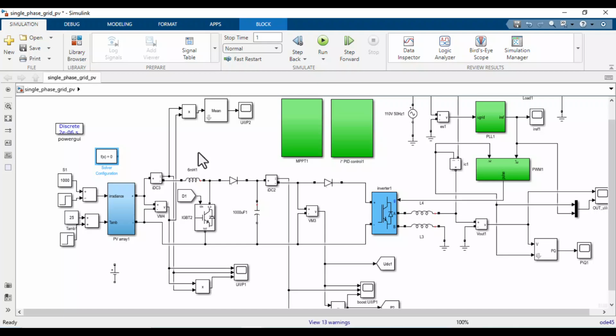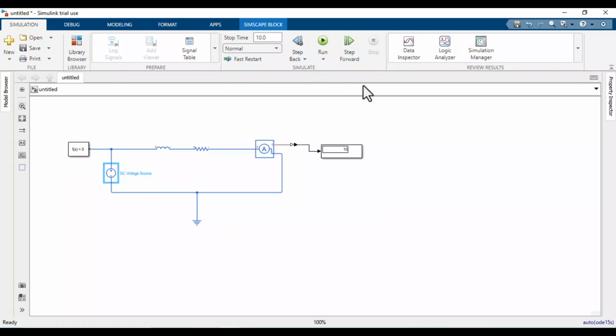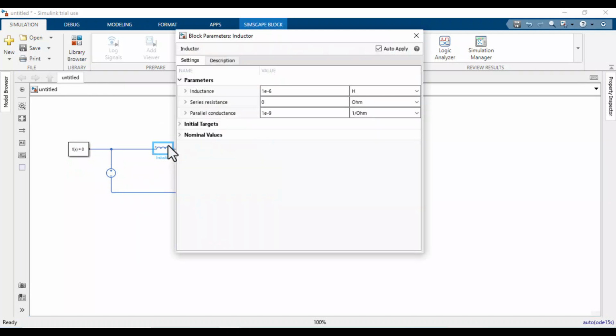The load flow analysis and steady state can be analyzed and built using Powergui in SPS. But in Simscape Electrical physical modeling, the initial condition of the blocks can be used for steady state analysis or load flow analysis. So we can change these initial targets.